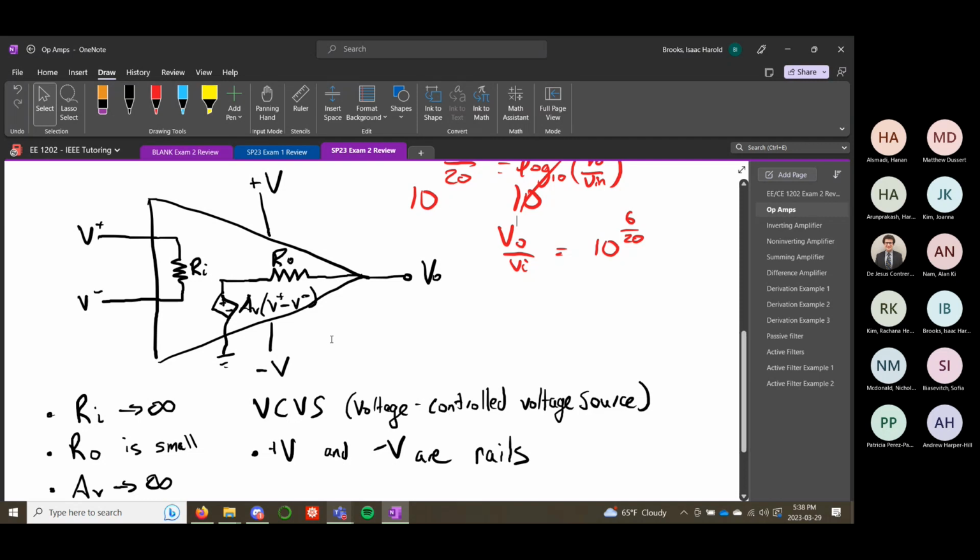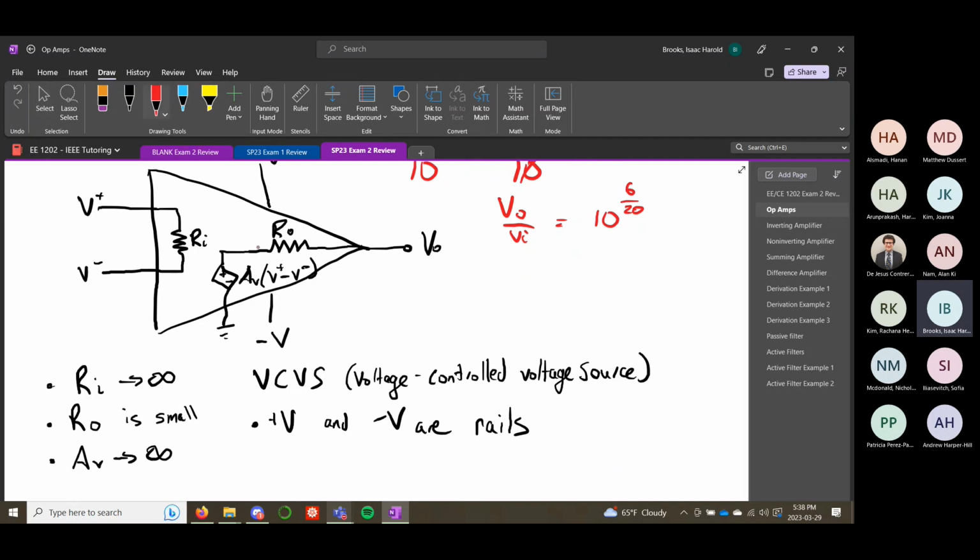So for your amplifier, or for any kind of circuit like this, you'd want a very large input resistance. If you think about something like a voltmeter, when you connect your voltmeter, you don't want any current to be going into it. So that's a high input resistance on a voltmeter. An op amp is similar. You want it to read the signal, but you don't want a lot of current going in if this is a high voltage. So you want to have a high input resistance.